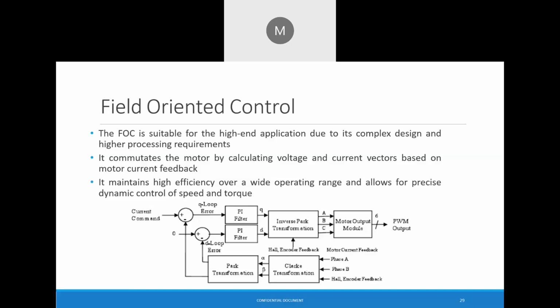Probably you can also consider various other parameters like temperature derating, the winding temperature, or the magnet temperature of the motor itself, and the board temperature of the inverter or motor controller board, because the high frequency switching of the IGBTs or FETs will create a very high temperature on the board, and that has to be controlled with respect to the various parameters, right?